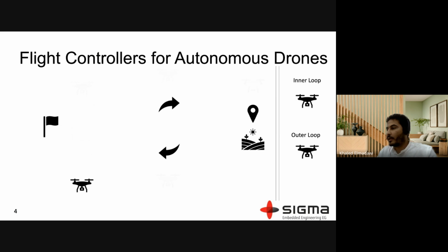The inner control layer is responsible for making the rate of rotation of the drone at a certain angle equal 0. So, for example, if the drone is required just to hover, then the required angle is 0, so it does not rotate. If the rate of rotation at an angle that equals 0, then the drone will keep in its place.